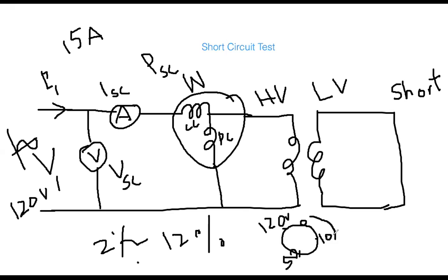You just adjust it. But as I said, at first you will keep this voltage at the 0 position. You make the whole connection, but you keep that knob setting at 0. This device is called the variac, which will be connected at this point. So the lab TA will show you how to connect that. I think they have already made 3 videos and I have uploaded those on the lab section, so you can see what I am talking about. This is called the variac.